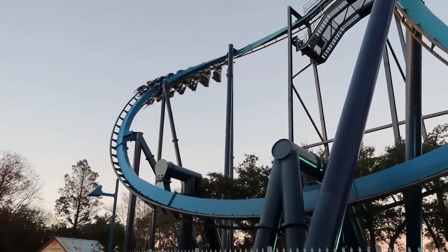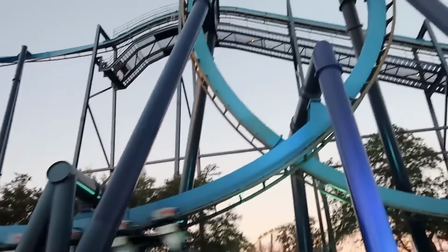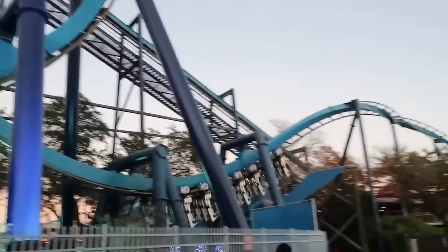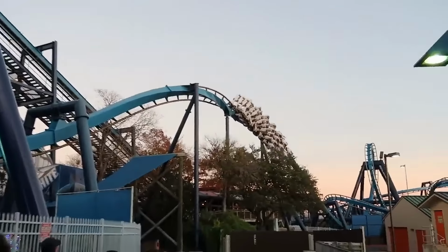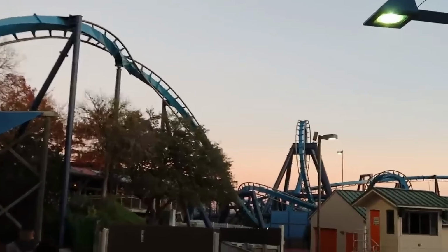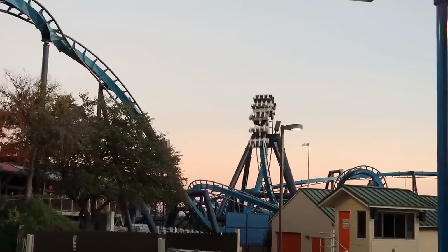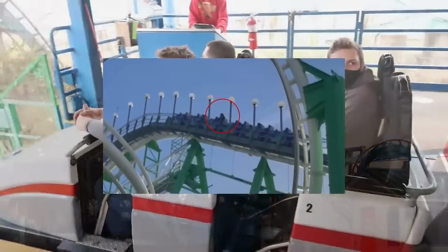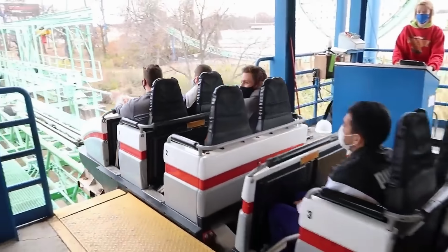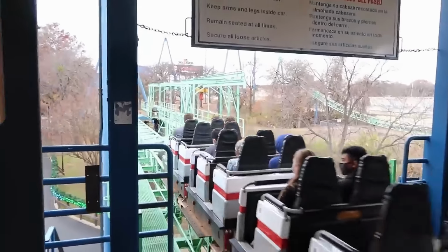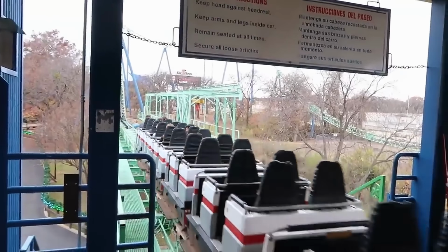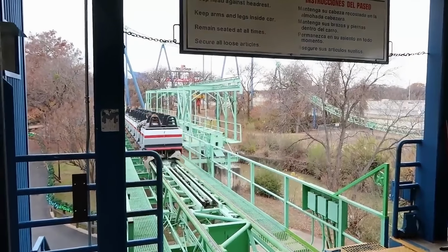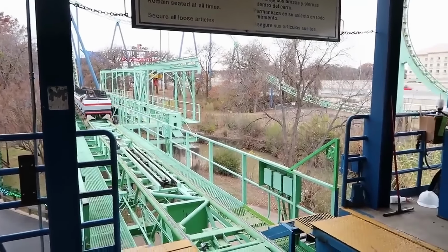This can be scary, and on some rides where the highest ratchet position is an allowed position for the restraint to be in, it can result in the restraint releasing entirely, though it will lock again if pushed down. This was the case for the highly publicized incident on the Desert Storm roller coaster at Castles and Coasters. In this case, a lap bar secured by a ratchet system slipped from the top ratchet, which allowed the restraint to be completely open. In this case, the rider chose to leave the moving train rather than to pull the lap bar back down, where it could have been resecured.